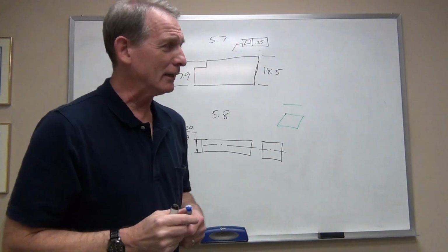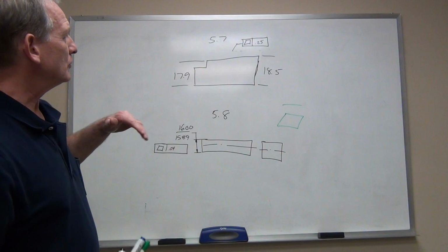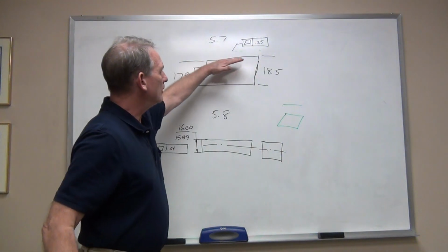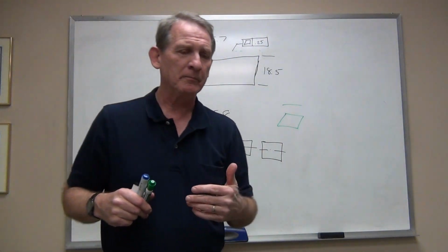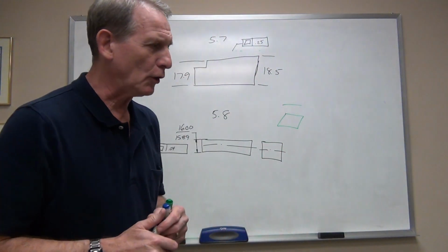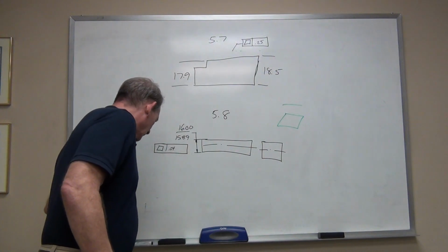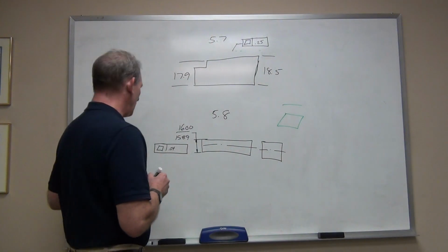The careless machinist didn't put it in the vise properly or something. It was tipped a little bit, and he milled a little bit of a bevel or a slope to that surface. Now we got to say, okay, so the flatness requirement still applies.